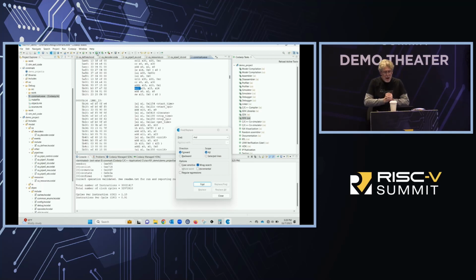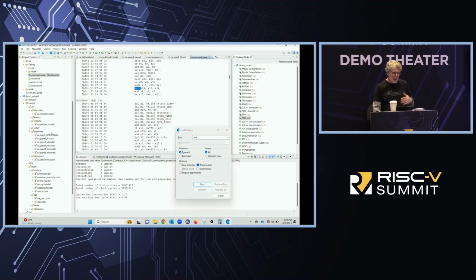Now, the nice thing about, if you once again go back to the basic core here of what I did, the basic 5-stage pipeline from David Patterson and John Hennessy is a register file of 2 inputs and 1 output, 2 reads and 1 write. So I can't do a MAC right now unless I make a multi-cycle MAC. But I really want my machine to go even faster, so I want a single cycle MAC. So I'm going to have to add some resources.